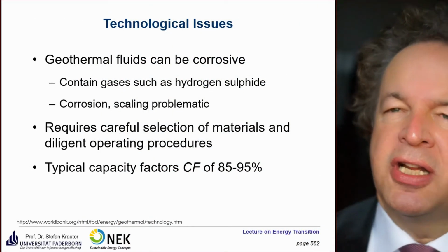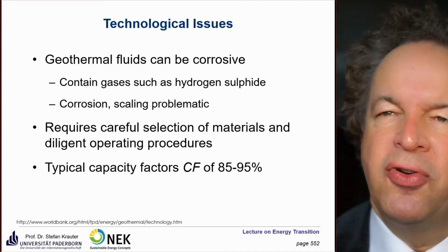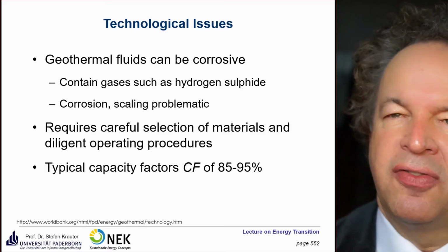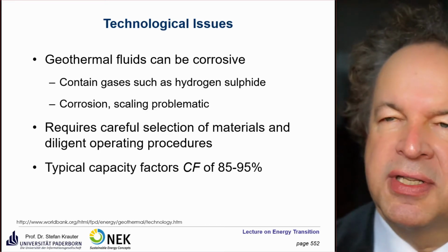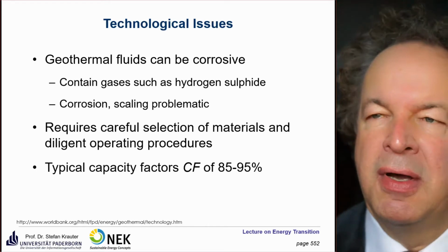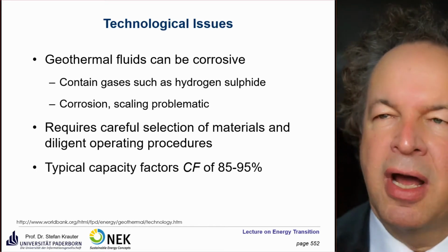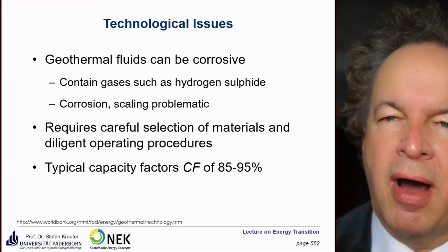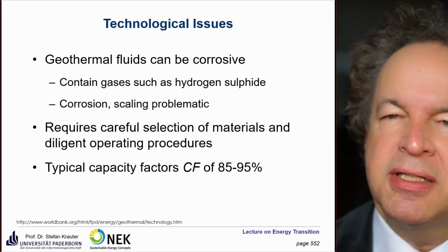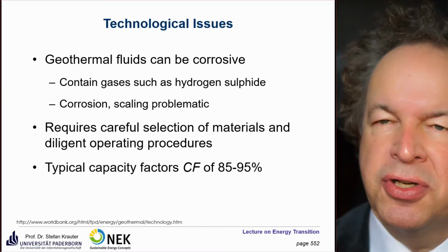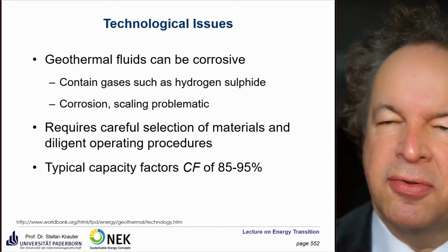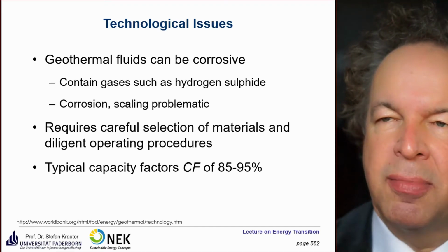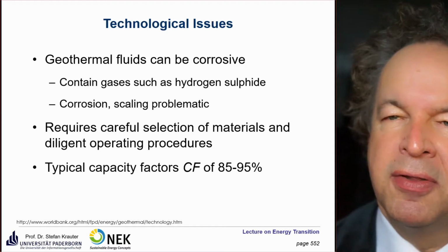The technological issues are that geothermal fluids may be corrosive. They contain gases such as hydrogen sulfide, causing corrosion. Also, scaling up is problematic because you sometimes only have a limited area where you can extract geothermal energy from. It requires careful selection of materials and diligent operating procedures. A typical capacity factor is 85 to 95%. If you compare that, for example, to solar or wind power, this is really high.